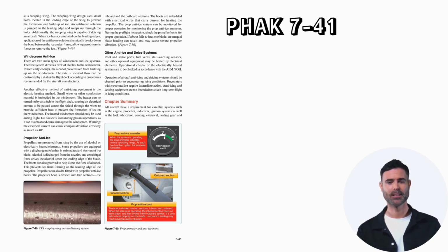Other anti-ice and de-ice systems, pitot and static ports, fuel vents, stall warning sensors, and other optional equipment may be heated by electrical elements. Operational checks of the electrically heated systems are to be checked in accordance with the AFM-POH. Operation of aircraft anti-icing and de-icing systems should be checked prior to encountering icing conditions. Encounters with structural ice require immediate action. Anti-icing and de-icing equipment are not intended to sustain long-term flight in icing conditions.